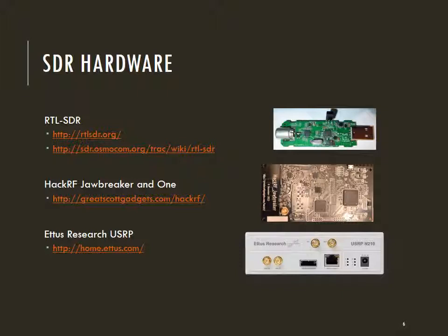The most important aspect of using these devices is that you need to get the right libraries. The libraries are going to allow your user-level applications to interact with your chip in conjunction with another library like libUSB. The range for these devices is somewhere between 24 megahertz and 1250 or 1776 megahertz, as you'll see on the next slide.